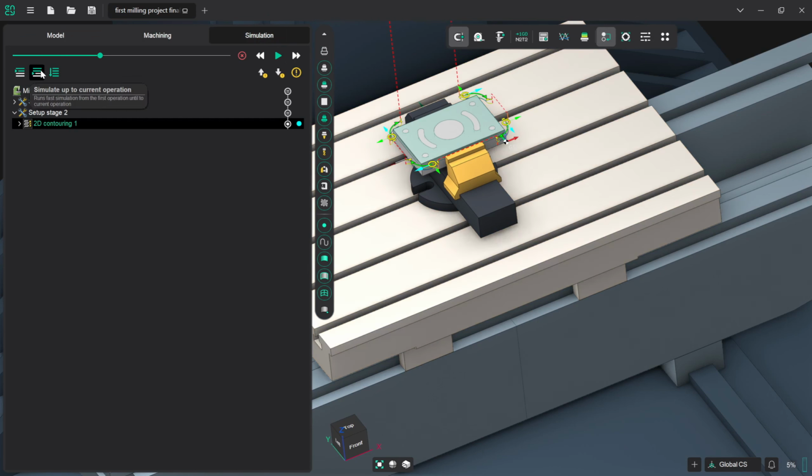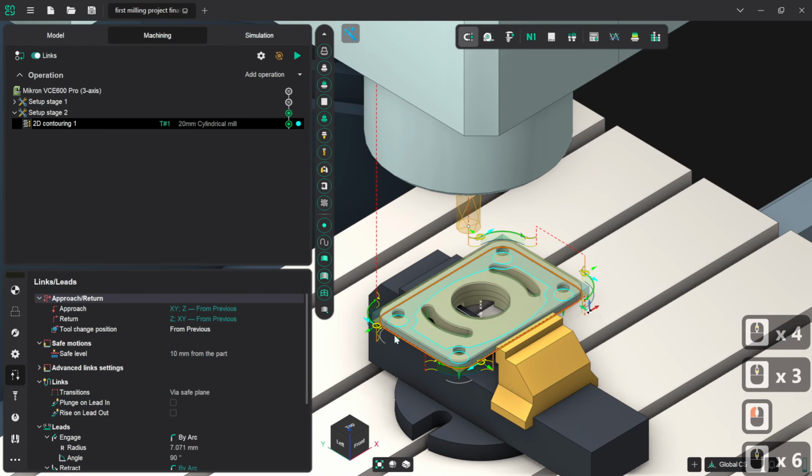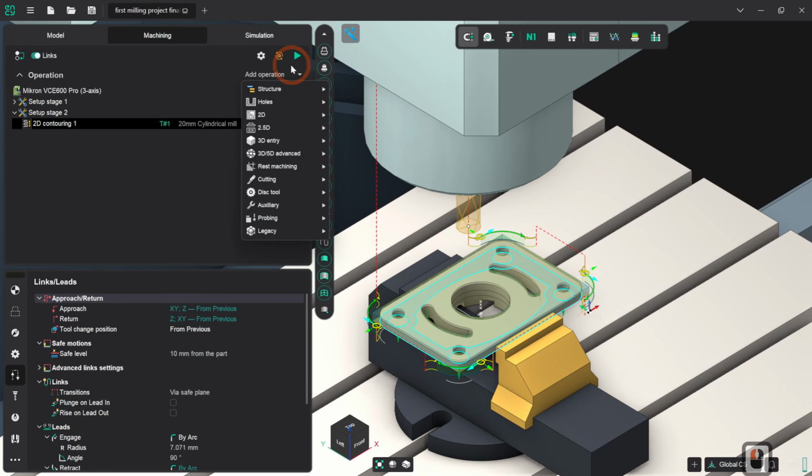And of course, the last machining operation that we want to define is we would like to face mill this. So I'm just going to snap back around to the cleaner view, and we want to face all of this off. So we're going to go to add operation, 3D entry, face milling, and we are going to check the setup just to make sure it's got the top and bottom levels right.